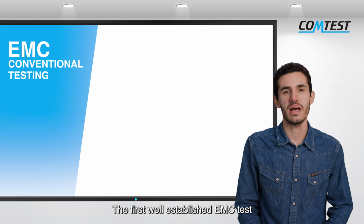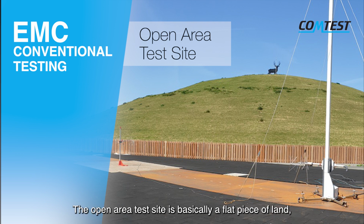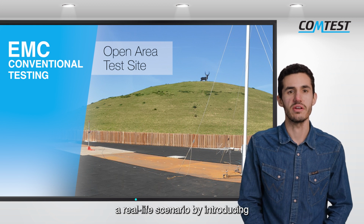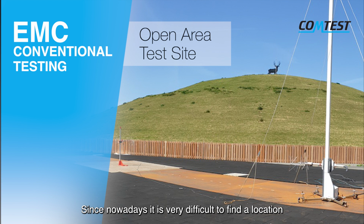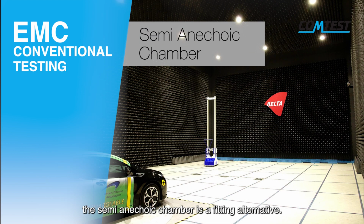The first well-established EMC test facility is the open area test site. The open area test site is basically a flat piece of land which is free of physical obstacles, RF surrounding signals, and equipped with a metallic ground plane. The use of such a highly reflective floor more closely mimics a real-life scenario by introducing and accounting a reflective wave from the Earth. Since nowadays it is very difficult to find a location not polluted by external noise signals, the semi-anechoic chamber is a fitting alternative.